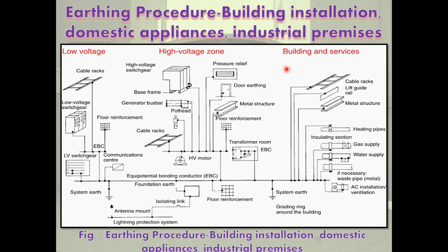Neutral earthing: to ensure that neutral points are held at earth potential and a return path is available to the neutral currents. Chassis earthing: to prevent electromagnetic noise or disturbance in measurement, control, protection and communication signals. Discharge earthing: to provide a discharge path to capacitive currents, earth return currents, and lightning and switching surges.